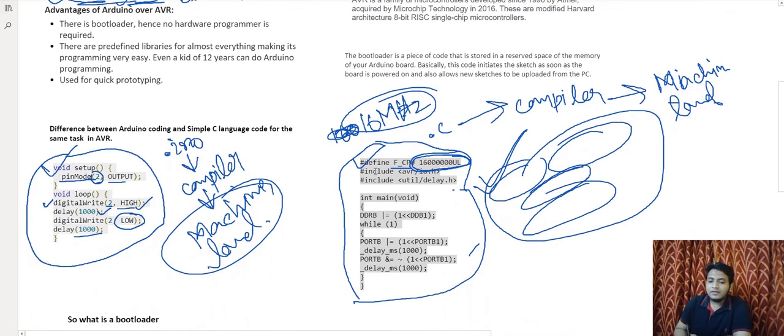And then we have to include the libraries, okay. This requires some programming language of C language, okay. And it has some utilities, and then what we have to do is port manipulation, okay. It is the data direction bit, so we have to set these things, and this B specifies that we are going to use port number B.